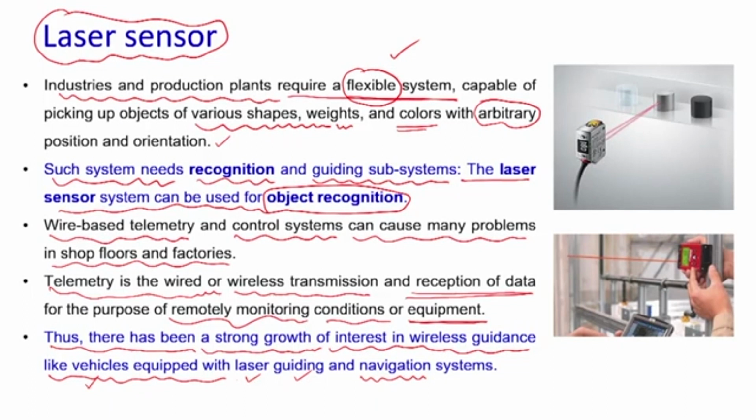Fine, on your screen you can see some parts. This is the white part. All the parts have the same geometry, but their color is different, and a laser based system can be used to detect the shape or the color of that particular part. When we apply the laser beam energy, the part or substrate reflects a certain amount of energy, and that reflection is the color of the surface. As we get the reflection, we can measure its intensity and its wavelength, and based on that we can easily recognize whether the part is of interest or not.